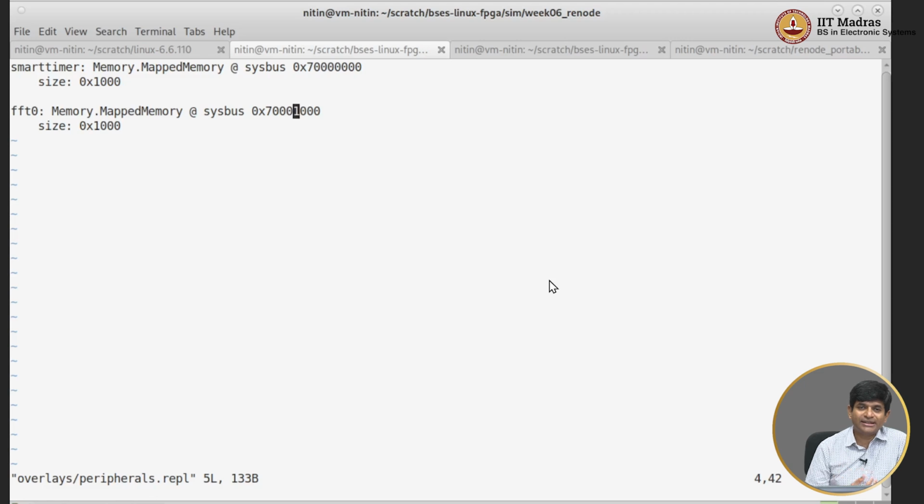And by doing that, as far as the Renode emulator is concerned, if you try writing into those locations, it will just take it and make a copy of it somewhere, because it will treat it as though you are creating a memory block at that point. If you try reading from it, it will give you back data corresponding to whatever you wrote there last. So Renode, in other words, is going to take care of emulating our hardware for us. It just creates a fake piece of hardware so that we can at least write and see whether the system is able to pick that up.